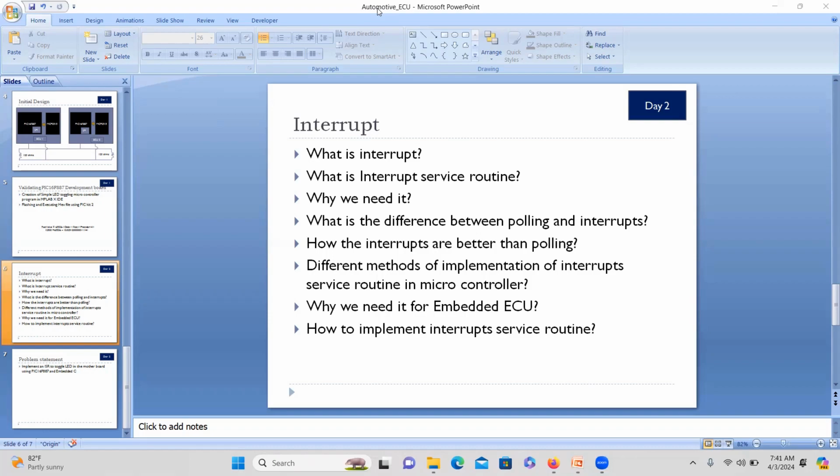So they used to provide you a table. If that particular event happened, the program counter will be loaded with that program address. Actually, the vector table is nothing but the vector, that is, program memory addresses. In those addresses, we used to give the addresses of the functions or the service routine that we want to run. We used to have a branch, or a transfer of control, from that memory location to whatever service we want. That is configurable.